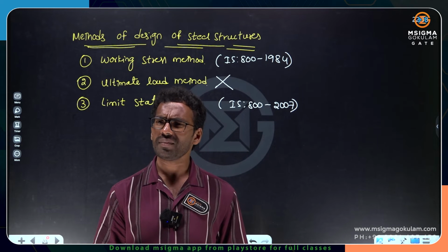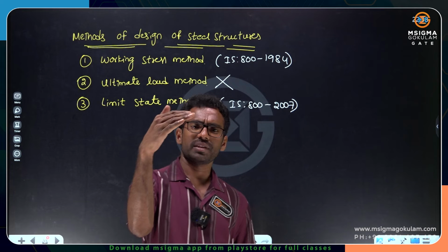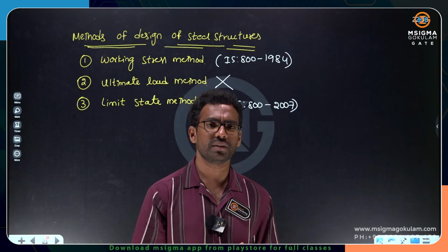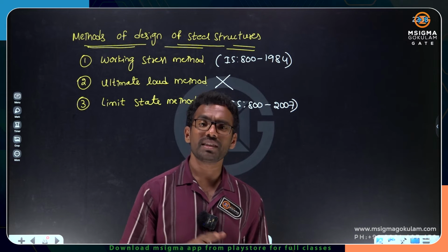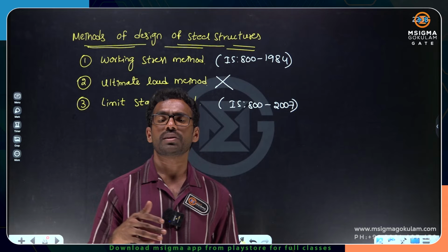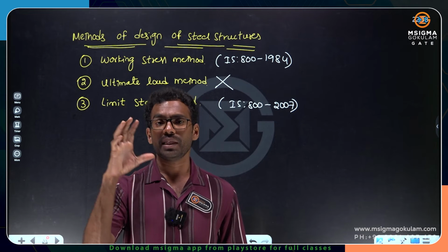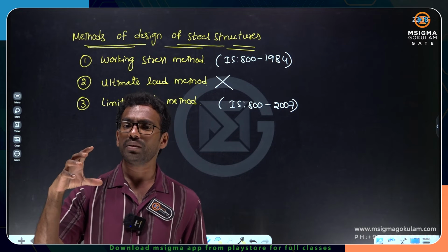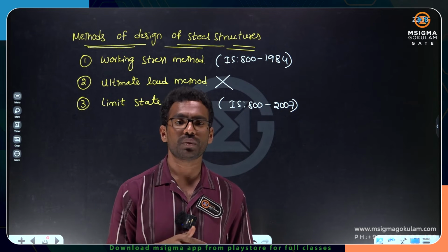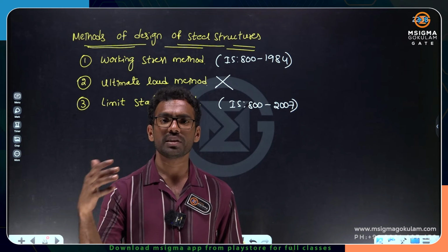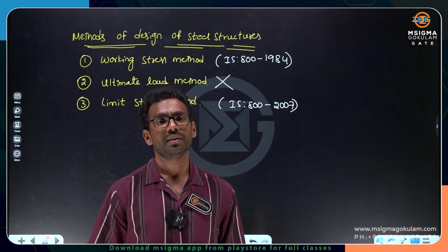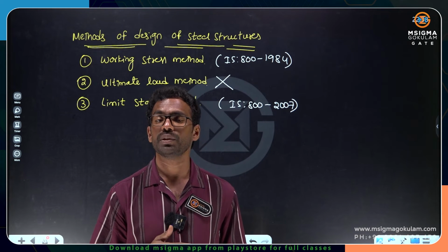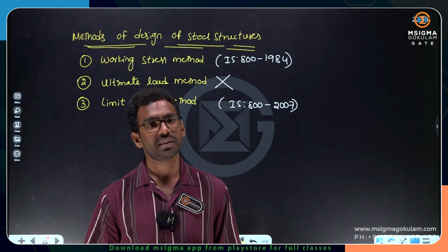When you use more factor of safety for material stress to keep the material at low stress, the area required for resisting a particular load increases. When the area is more, dimensions are more. When the dimensions are more, the investment is more, and people are not in a position to accept that. That is the biggest problem we have.